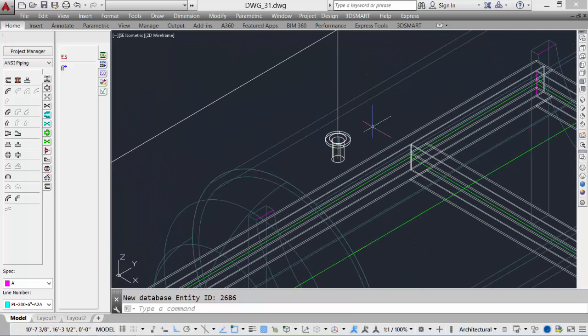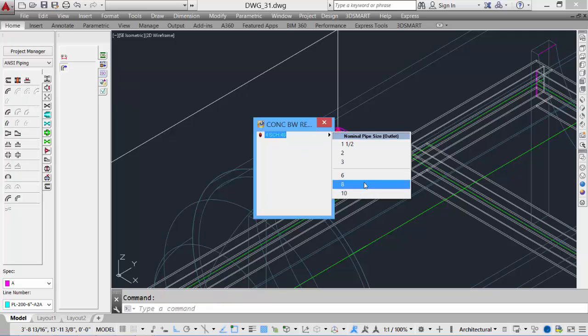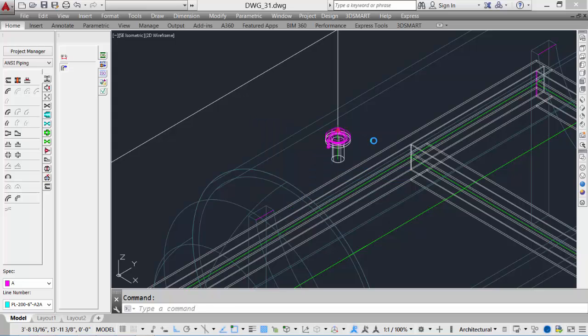We'll come off of the nozzle here, so we'll do autoroute, so mix and match of the autoroute and place relative. Go to our flanges, pick our gasket, pick our connection point, and then we'll pick our flange and our bolt set. Let's put in a reducer, so back to fittings, put in a reducer, and we'll go from our 4-inch up to our 6-inch pipe size.